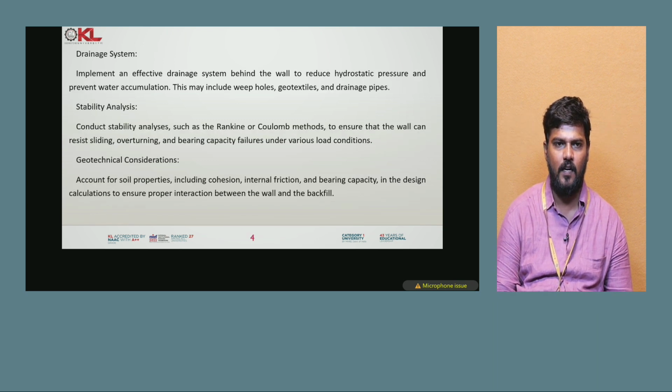Next one is the drainage system. Implement an effective drainage system behind the wall to reduce hydrostatic pressure and prevent water accumulation. This may include weep holes, geotextiles, and drainage pipes.